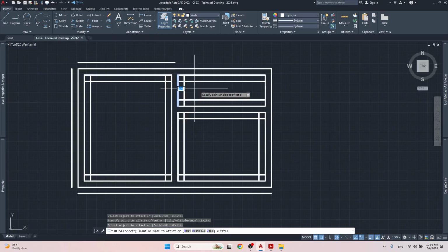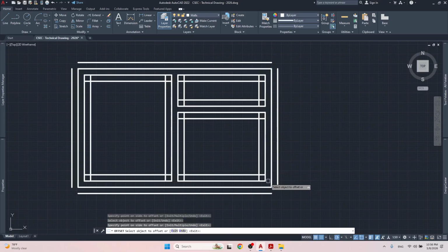Please take your time, try your best not to get confused. What you could also do is offset one side, one room, and clean it up immediately. So fillet, multiple, clean this up. You could clean it up as you go along so that you don't get confused. All right, so there we have that. That's that room. This is the storage, the foundation under the storage, like so. And let me clean up here, connect these.